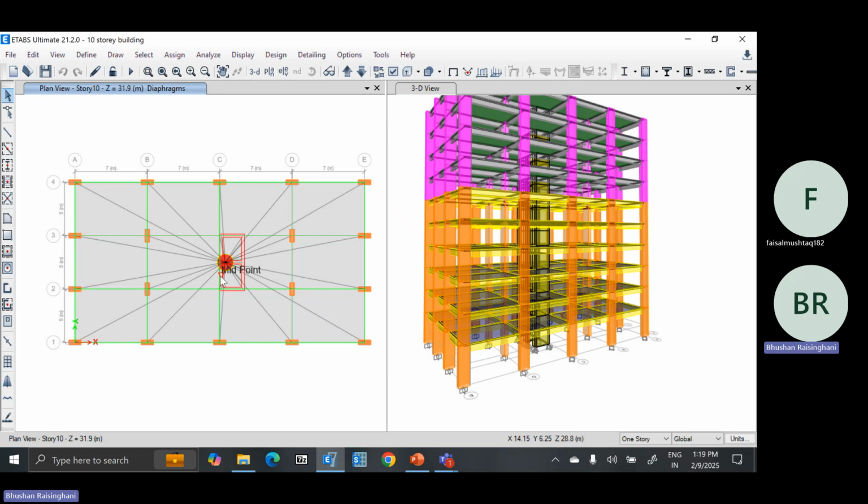So at the stilt floor or the refuge floor at the 7th or the 8th floor, I will have to take the water tank on it, the firefighting tank. That firefighting tank area has to be defined by the architect, where the tank is going to be, and on that area I will apply the water load, right? And on the OHT also I will create columns or whatever the arrangement is there, slab, beam, column arrangement, and apply the water load on the OHT as well.